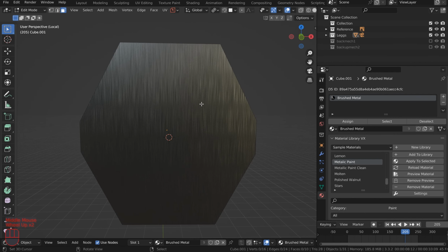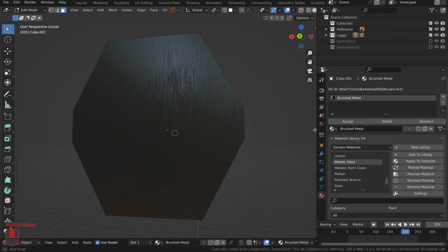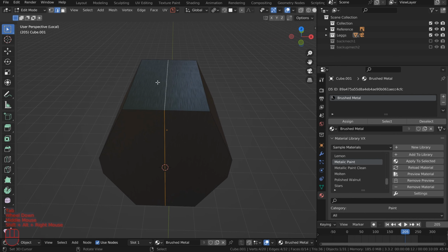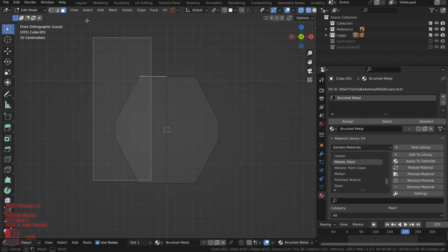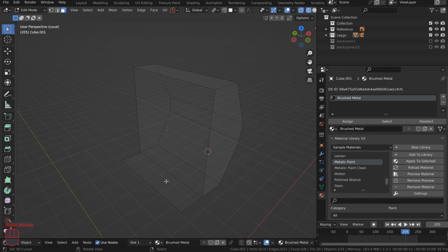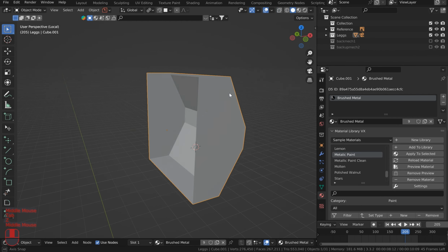So this one's a little bit more stubborn, so I'm just going to hit the K tool, and I'll bring it as close to the center on the Z as possible. Click it, hit A, perfectly straight line, bring it down, press C, and then click and enter. And now I should have that loop perfect around the edges. A little more destructive, but it works. And so now I can just select these faces, go into wireframe, just select those, and we will delete those faces. Delete that face as well. Let's jump back over to solid.